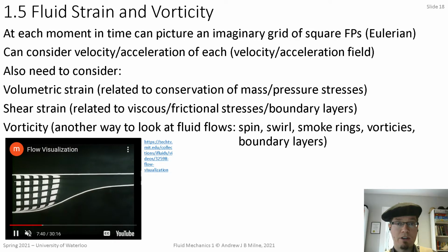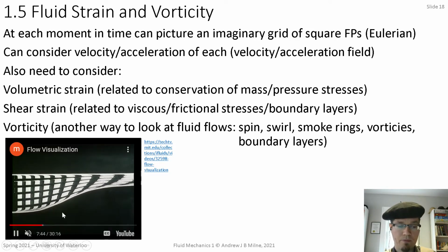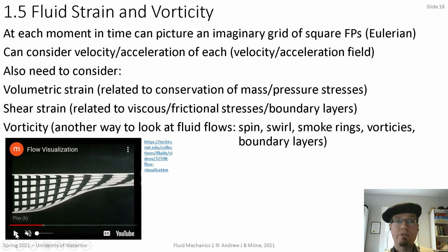So this is the same converging channel as before. I'm going to pause it for just 1 second. But instead of marking single points with fluid parcels, we are marking all of them in that sort of grid there. And you can see that from left to right, any given square gets stretched out. So that's to do with the volumetric strain, the stretching and squeezing.